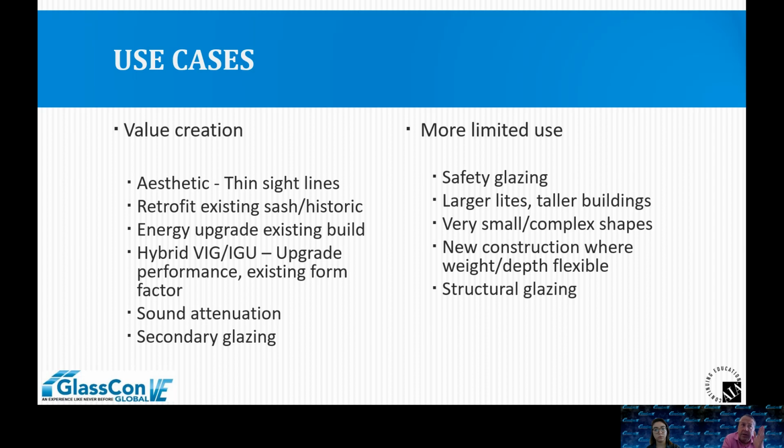So if you think about typically, storm windows, we add maybe a hard coat low E, and you get a nice upgrade in your energy performance, but it's not the same level as a code compliant. There are trade-offs in that. But if you talk about using the VIG as your glazing material in your storm window, now essentially you have a retrofit solution that gets you to pretty much triple glaze performance.